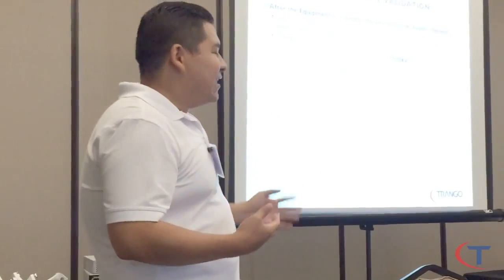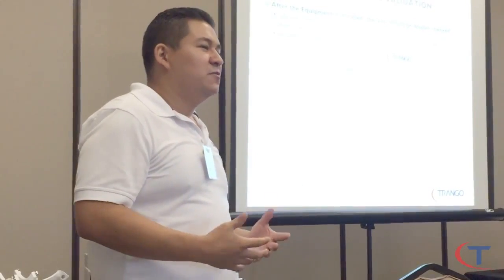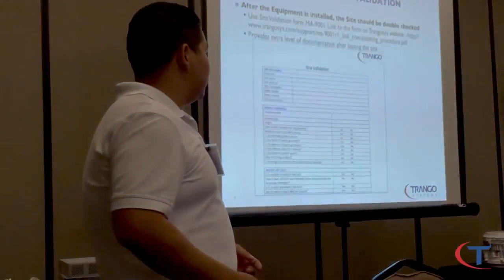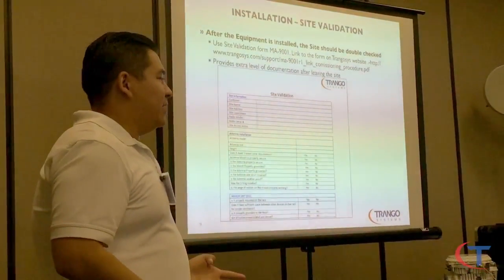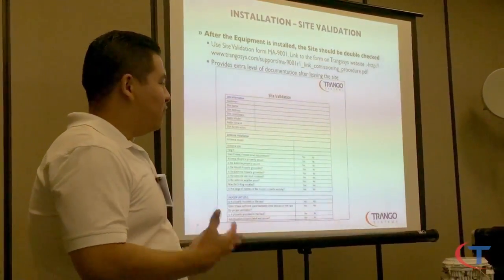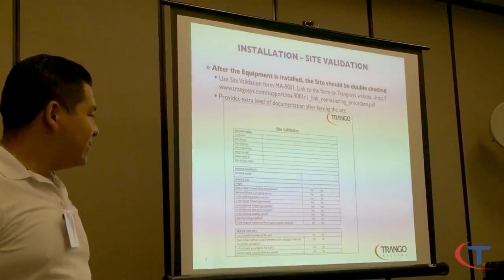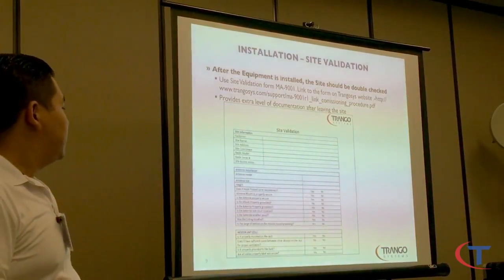So, site access notes: document as much as possible, get every little detail down. Antenna installation, antenna model. Is it a T2 antenna? Is it a 4-footer, 6-footer, whatever it is? Antenna height, make sure it actually matches.